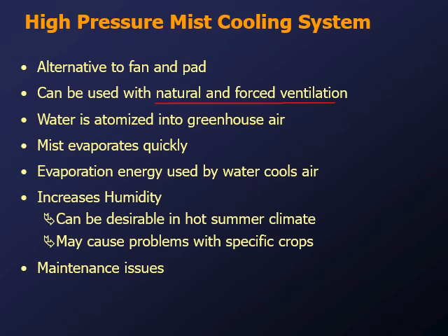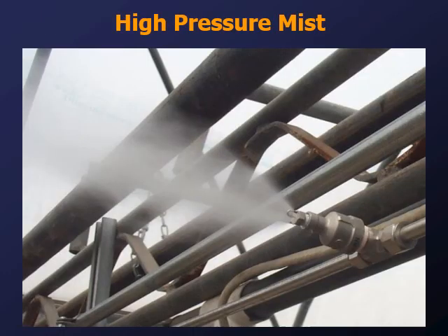Maintenance, yeah, with such fine nozzles, if you've seen drippers plug, you can only imagine how much these other ones plug. So you have to deal with the water treatment to make sure there's no calcium in there and stuff like that. There's a close up of a high pressure stainless steel line in the greenhouse, and then there's your fogging nozzle.